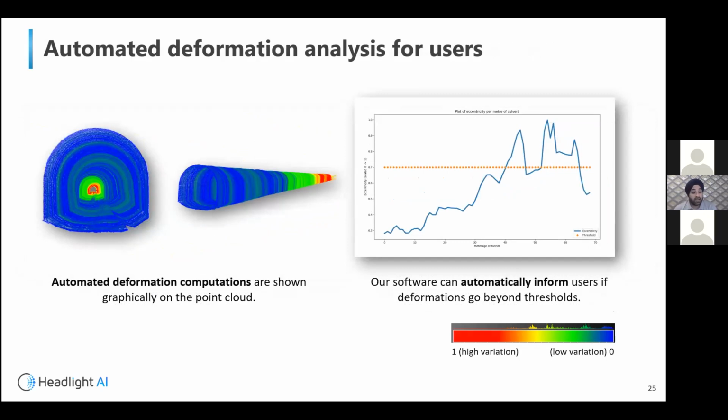We also then looked at what happens to the shape, and again with the same idea in mind to build a holistic view of the whole pipe. We then started looking at some variations in the shape. The culvert that Jameel just showed you right at the start with lots of cracks is one of the most interesting ones, because the earth above was actually pushing in, and you started with a very symmetric shape, and then as you got into the culvert, it became more isometric. And that is highlighted here with the various colors.